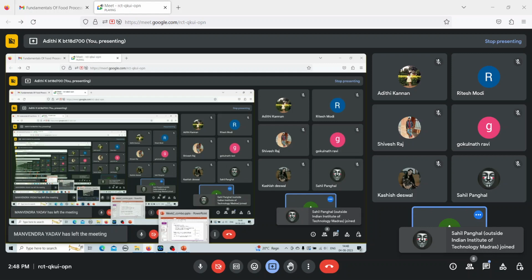In the case of a viscous behavior, my stress is proportional to the rate of strain. So here you have sine of omega t plus 90 degrees, which means you have a phase shift of 90 degrees. If you start giving strain right now, you will be able to see the sinusoidal nature of the stress only 90 degrees after. So there is a phase shift of 90 degrees. This is for an ideal elastic behavior, and this is for an ideal viscous behavior.